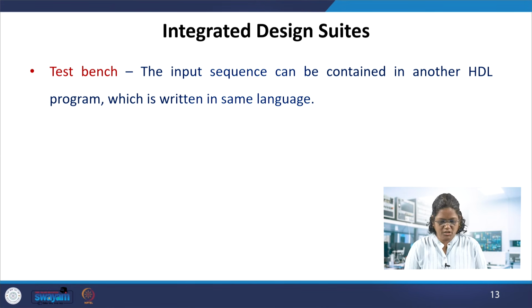And the test bench sequence is another HDL program. As I said, the inputs which are needed are put in the Verilog code, written in the same language, either VHDL or Verilog. So the test bench holds the inputs which you want to test for the design you have. It can be a simple AND gate, or a decoder, or a multiplexer, or a filter in DSP. Those inputs are put in the test bench in a time sequence manner, and then given to the design through the simulator, and the function of the design is verified and the outputs are visible.